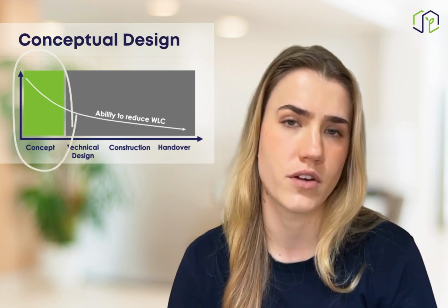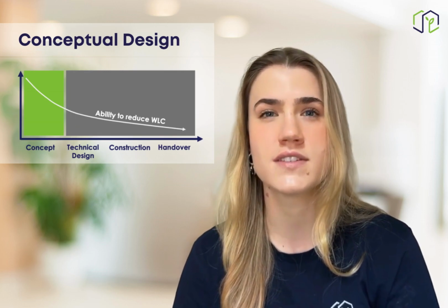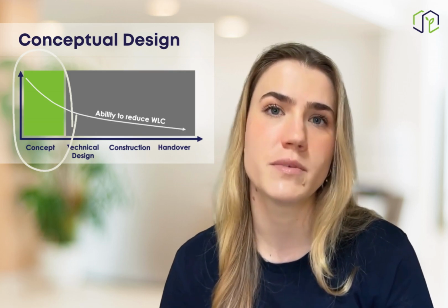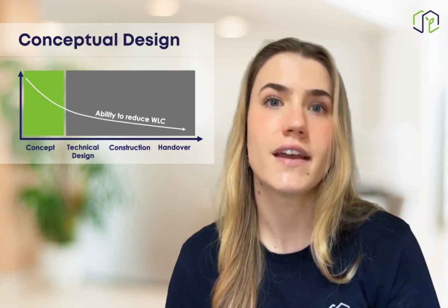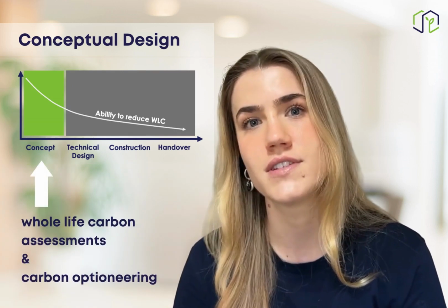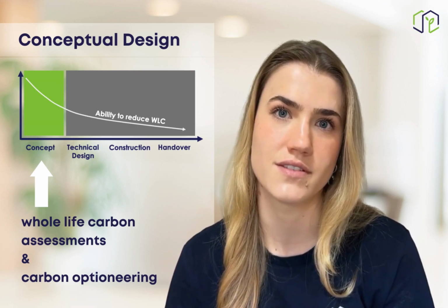An early stage approach is far more effective than compensating later with small reductions made during technical design or material procurement, or even through energetic retrofitting, which can sometimes lead to a net increase in embodied carbon if the materials used have long carbon payback periods. Integrating whole life carbon assessments and optioneering into conceptual design is in fact the best way to avoid significant emissions.